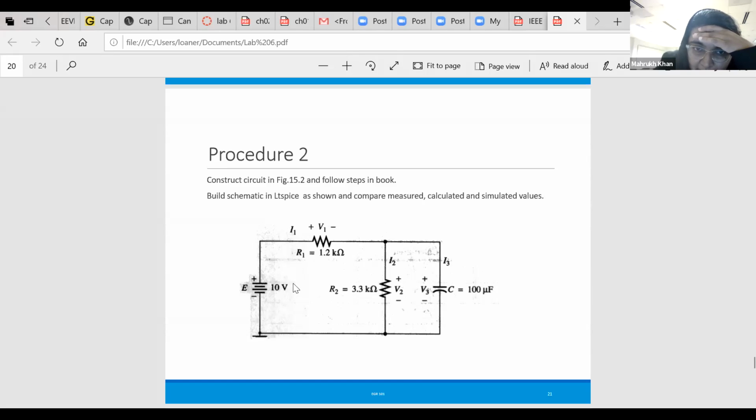This circuit will open once you disconnect the battery, and the capacitor will discharge across this resistor, and the current will start flowing in the opposite direction. Okay? Oh, all right, I get it. Because the capacitor will start acting as a battery once you take out the existing battery source. Yes. All right. Got it.